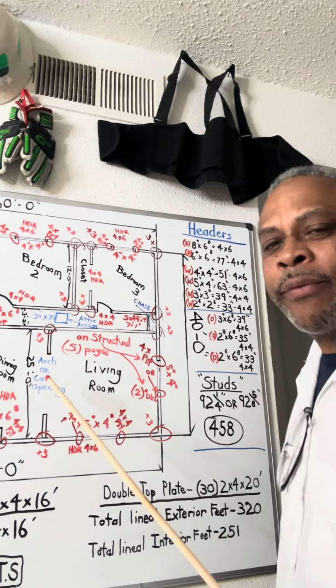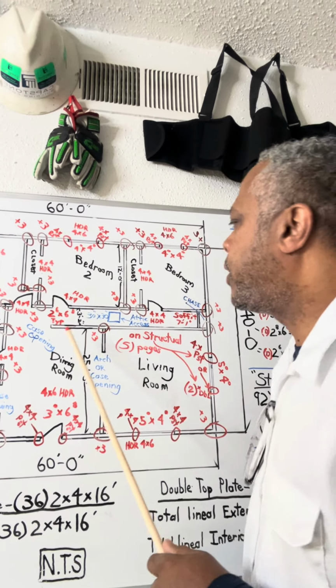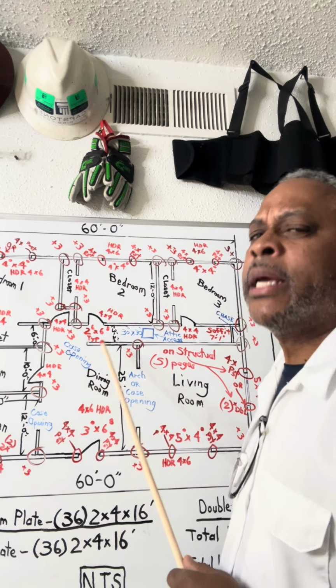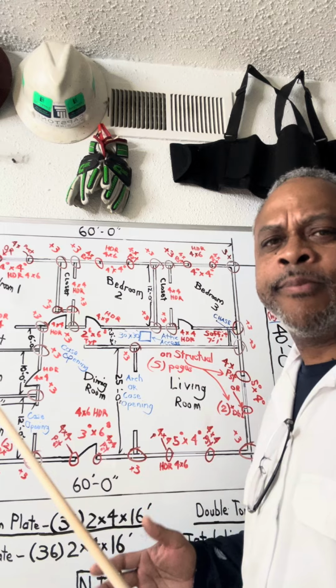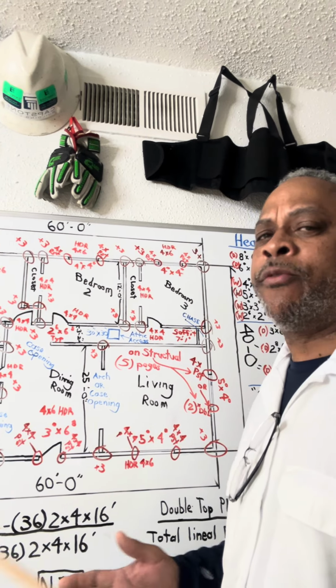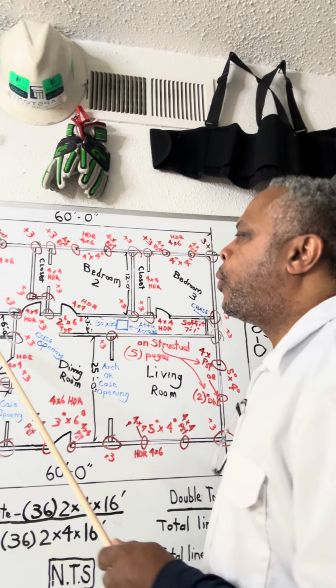Okay, so I do have some dimensions here. I have 25 feet from inside to inside. I have 3 foot for my hallway. Most hallways, 3 foot. Once you drywall it, if you have 1/2 inch on each side, you do want that 3 foot clearance. You don't want to go under 3 foot. That's like a code. Okay, so we do have a closet space.